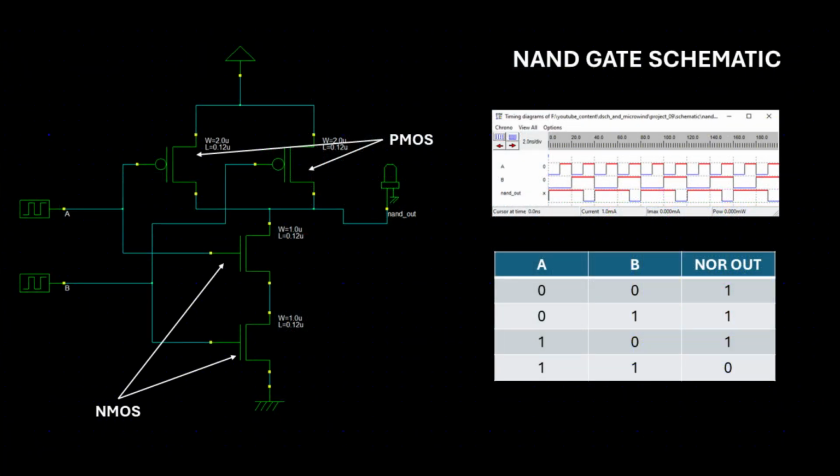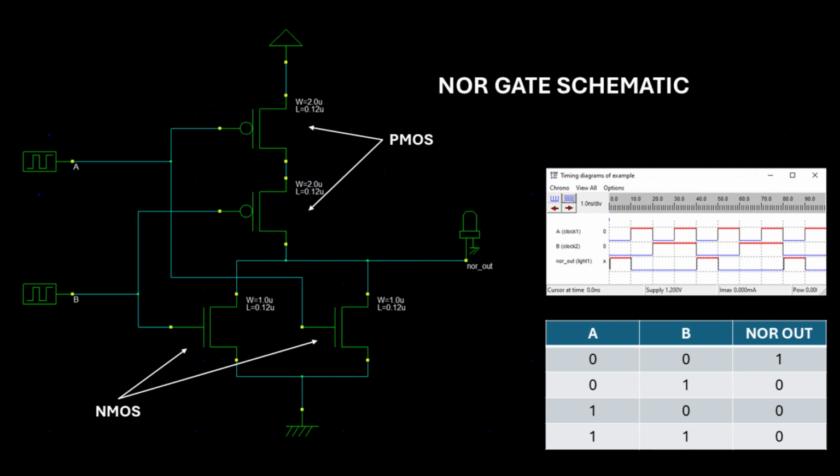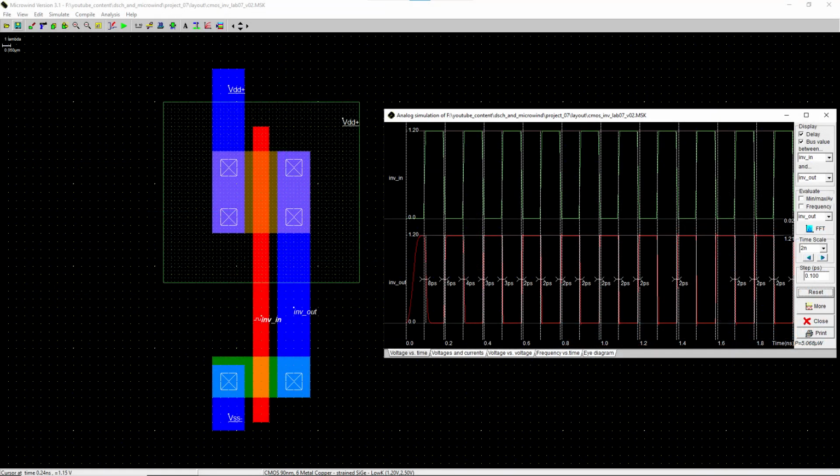In previous experiments, we used the basic gate layout provided by the Microwind layout entry tool. We also used the PMOS and NMOS transistors provided by the DSCH Schematic entry tool. We utilize schematic to Verilog conversion and Verilog to layout conversion to implement area-optimized layouts for complex gates.